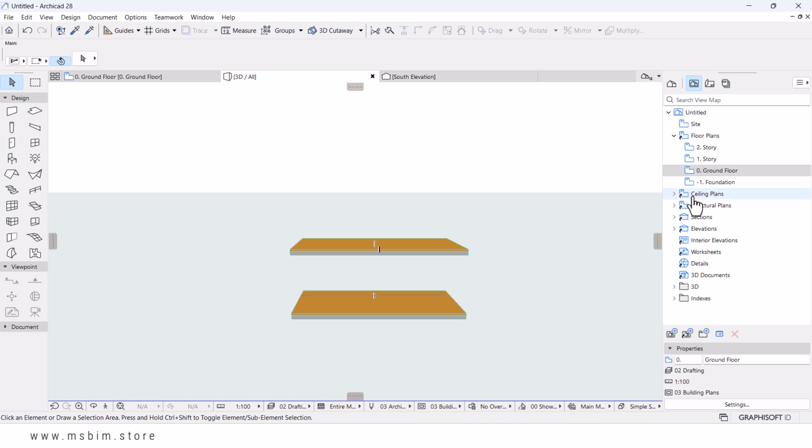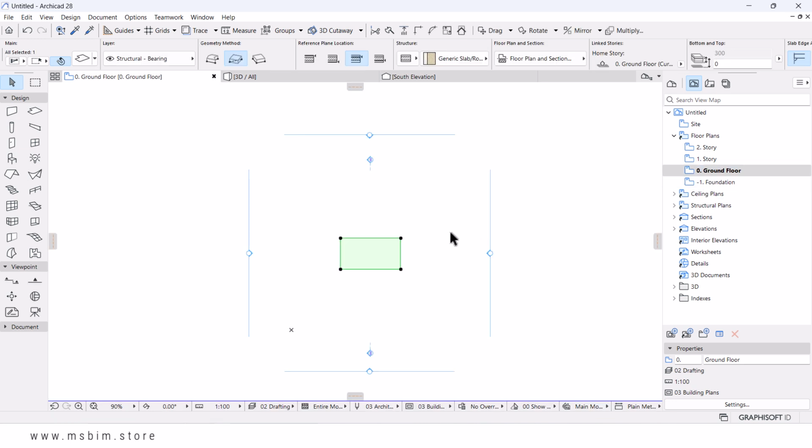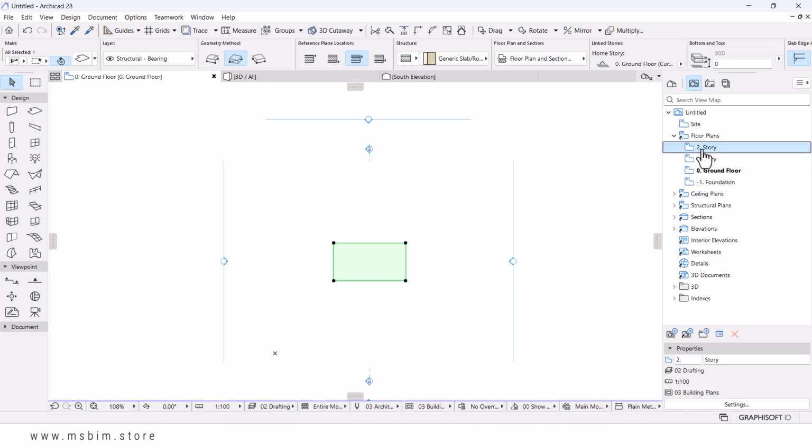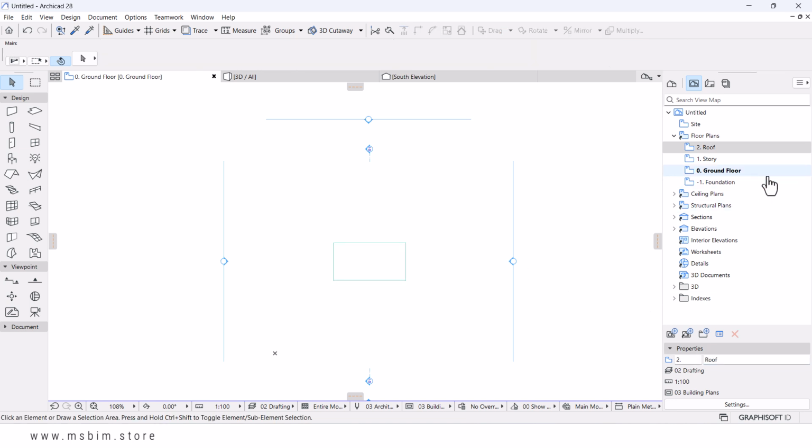So let's go back to our ground plan view. I think to avoid confusion, we have 3 floors here. Let's rename the last floor so that it can represent the roof. So I'm going to right click. You can either do it in the properties here by selecting the story 2 and then renaming it to the roof. But because we're going to use this information in our sections and elevations, if you are overriding it here, it's not going to be captured on our elevations. So it's very key to do it in the story settings.